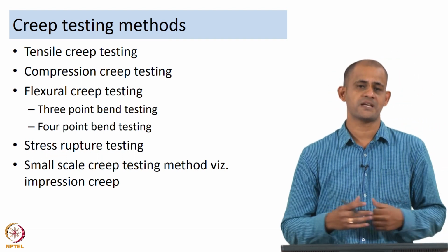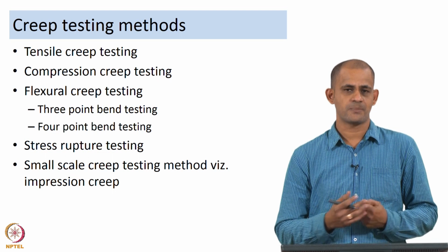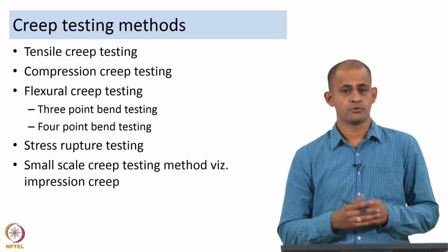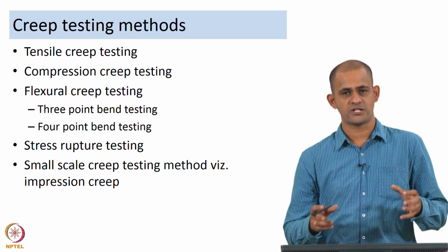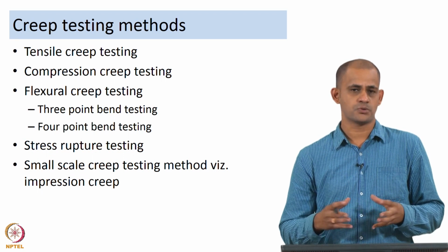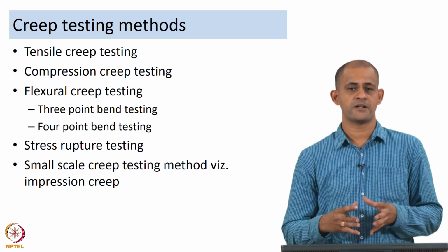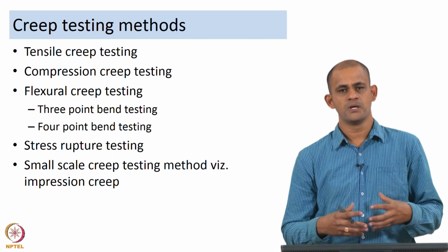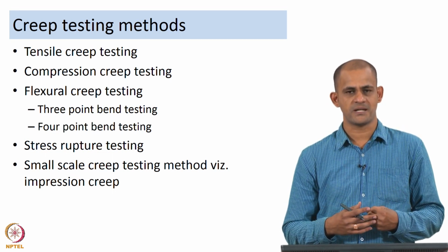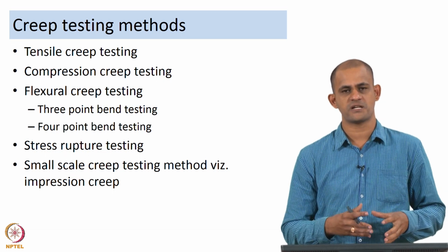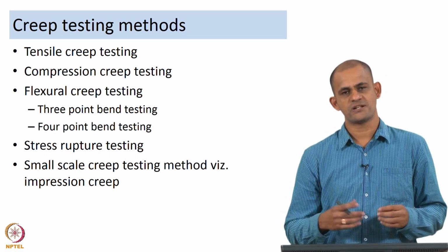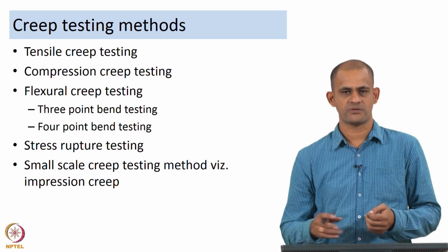Creep testing can be carried out under tension or under compression. You could also carry out creep testing in the flexural mode, and there are certain creep testing methods which involve stress rupture under internal pressurization. If you have a tube of which you want to study the creep behavior, you can internally pressurize the tube with some inert gas and study the change in dimensions as a function of time.